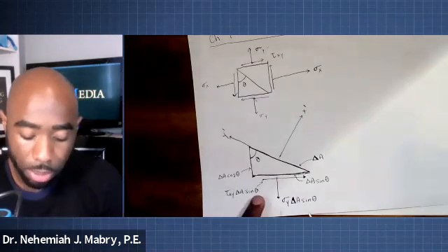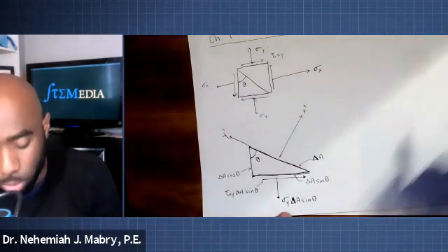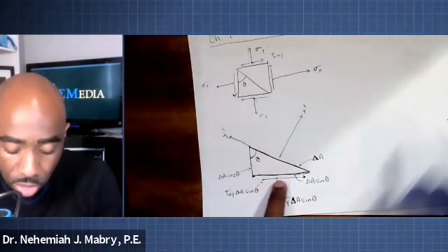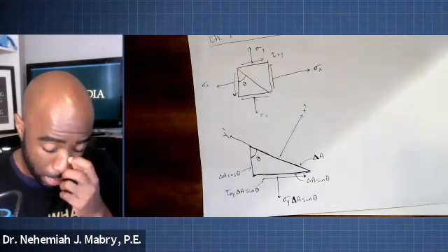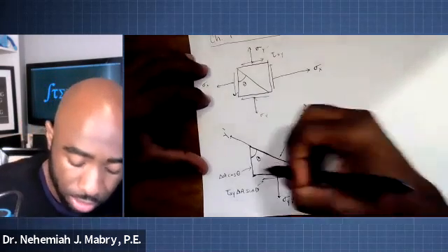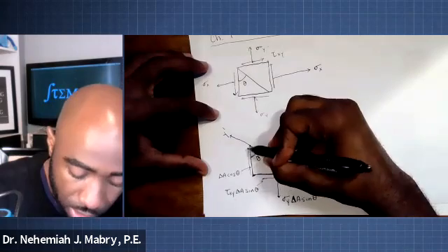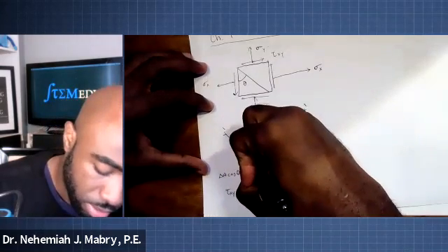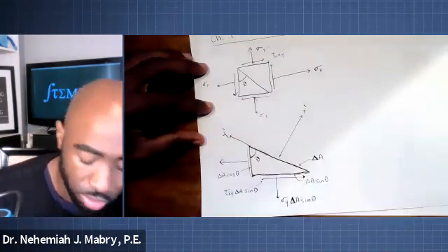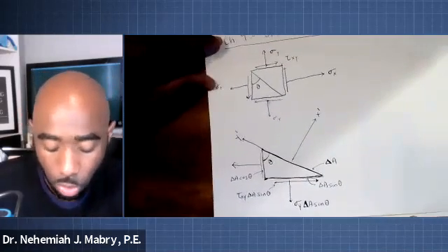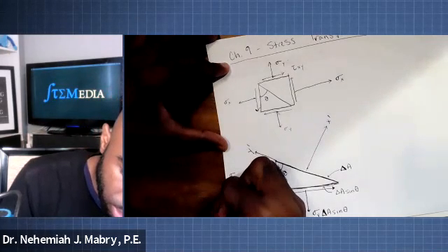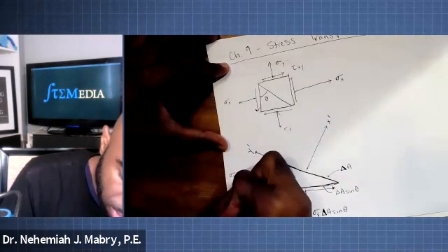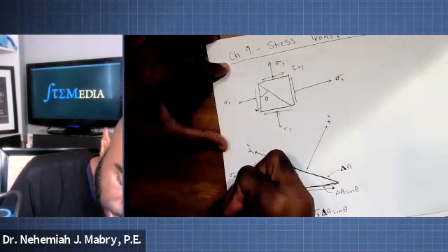That's how we're going to write our stresses on each side now, because we're looking at it as a new orientation. We're going to multiply the value times that surface area, delta A sine theta. All right. Likewise, if we were to do the same thing for the shear stress and the normal stress on this side, what would it be in that case? Well, the normal stress would be sigma sub x delta A cosine theta.